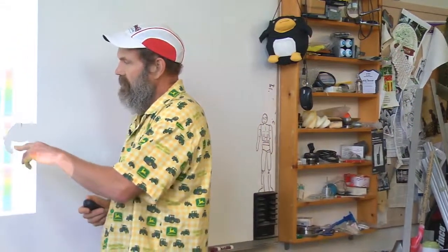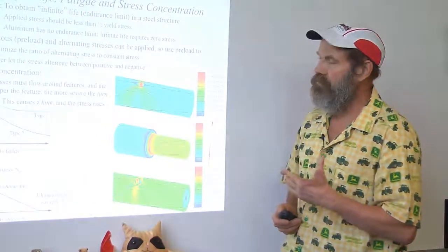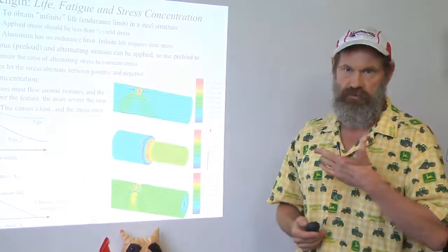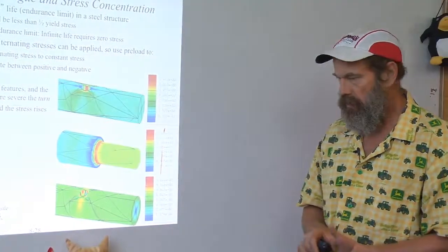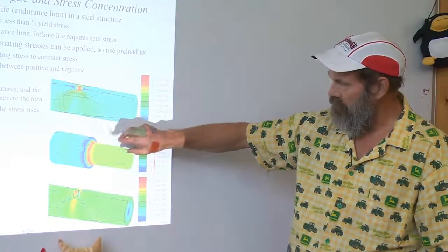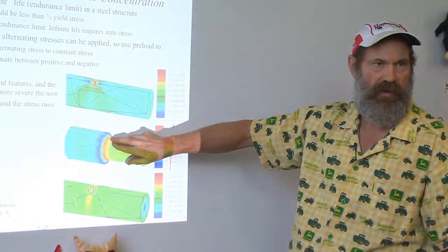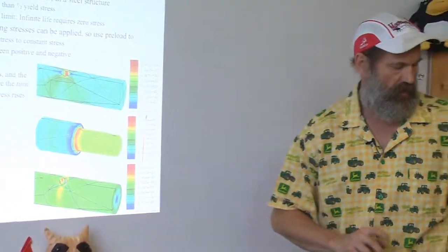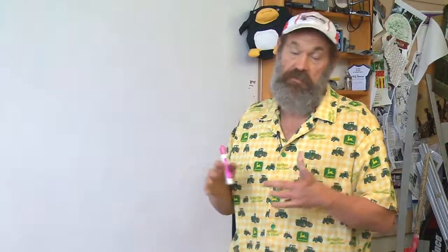Now, when you're doing finite element analysis, you've got to be very careful that the mesher, either inherently inside of it, will do a very fine mesh, or you have to control with the parameters you can use the size of the mesh to give you accurate results. One of the very important ways you can know how fine the mesh has to be: most finite element programs will allow you to just use the default, or you can tell it to go finer.